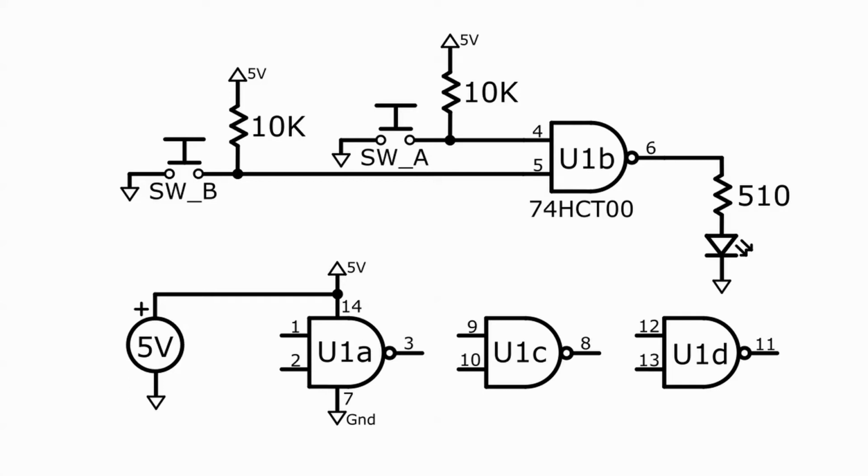Before proceeding, I need to make 2 more additions to the circuit. Firstly, I'm going to add a capacitor as close as possible to the power supply pin. This capacitor helps to protect the chip from noise. Electrical noise consists of fluctuations in current and voltage which race through a circuit when things change. It always takes a bit of time for a circuit to settle down after something changes.